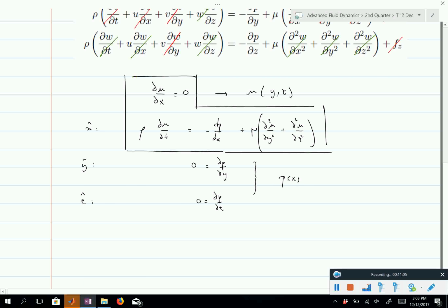Now note again, the important point here is that I don't have any inertial term here. There is no inertial term. I mean, I have an unsteady term, but I don't have a term really due to inertia here. The nonlinear term is gone. And when the nonlinear term is gone, we have some hope to have analytical solutions. Right? As long as the nonlinear term is in there, don't even try to ever integrate Navier-Stokes equation. You won't. Yeah, it's not going to be a success. It's not going to help. Okay. Hold on. There's one more thing which I want to do.